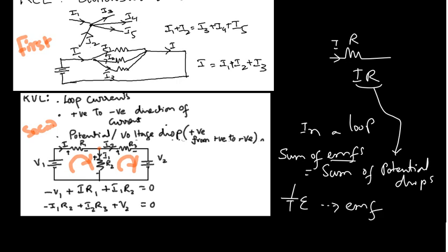So now if you look at this loop, on the left side, here in this loop we have one EMF, this one. In this loop there is another EMF. I could have written it a different way, but I chose to write only one EMF in this loop. This is loop 1. So EMF equals, here also voltage dropping, here also voltage dropping. How much voltage drop here? I R1. So that's equal to I R1 plus how much is the voltage drop here? I1 into R2. So that's an equation for this loop.